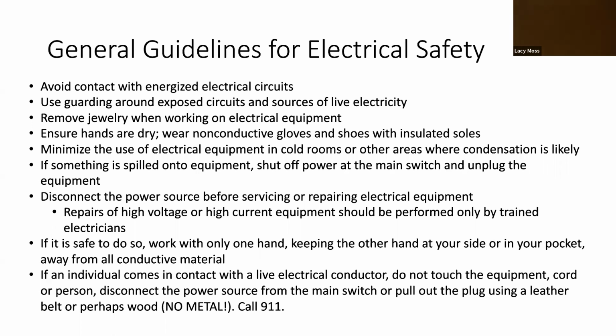Disconnect the power source before servicing or repairing electrical equipment. And if it's high voltage, get a trained electrician to come in. Don't try to do it yourself. If it's safe to do so, work with only one hand, keeping the other hand at your side or in your pocket, away from all conductive material. So you're kind of like James Dean doing stuff over here.